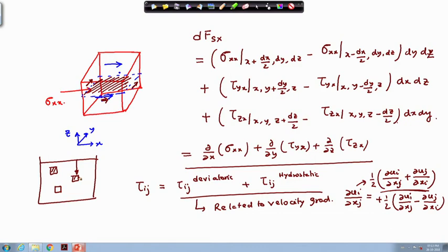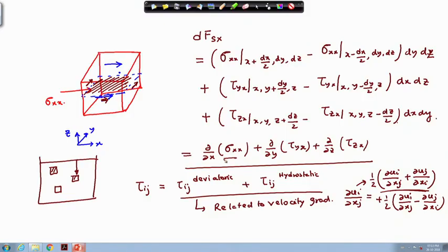So, this is called the hydrostatic component of the stresses, which is related to the pressure that is acting or the pressure gradient. So, kindly refer to the handout for the details of this. It would be very good if you can introduce this concept, so essentially the pressure gradient becomes a component of the normal stress, and if you expand this particular term into the hydrostatic and deviatoric components, then depending on the situation you will have the appropriate pressure gradient.